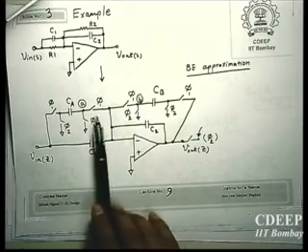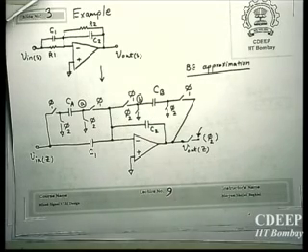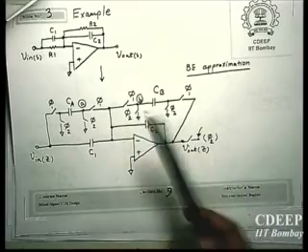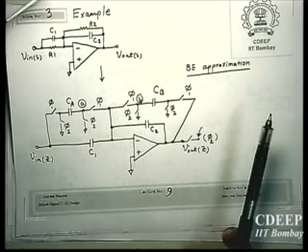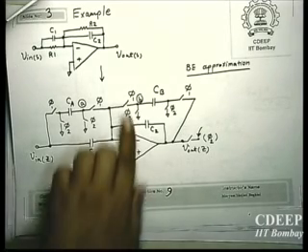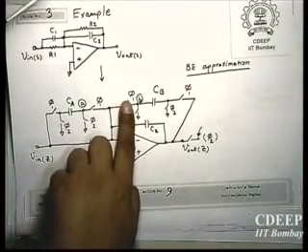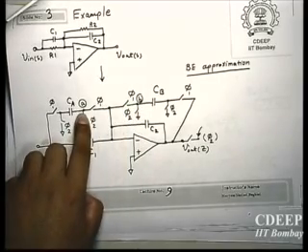And then, of course, nothing will happen when phi 1 and phi 2 both are 0. Therefore, what we will do is that we will remove two of these switches, because after all, we know that these two switches follow each other when we need. And when phi 1 and phi 2 are 0, no transaction is happening. So we just remove two of them and we share this. And because we are removing, we need to connect this node to a switching node. That's why we connect B to A.